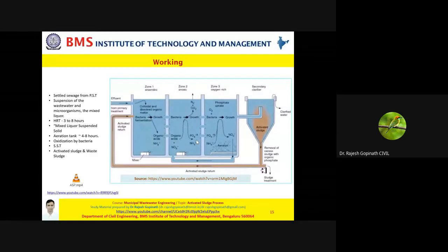Okay, in your aeration tank there are microorganisms which are already present. Please understand that there are certain assumptions which are made when it comes to your ASP. Assumptions such as, there are no microorganisms present in your primary sedimentation tank. That is the first assumption. Microorganisms are present only in your aeration tank.